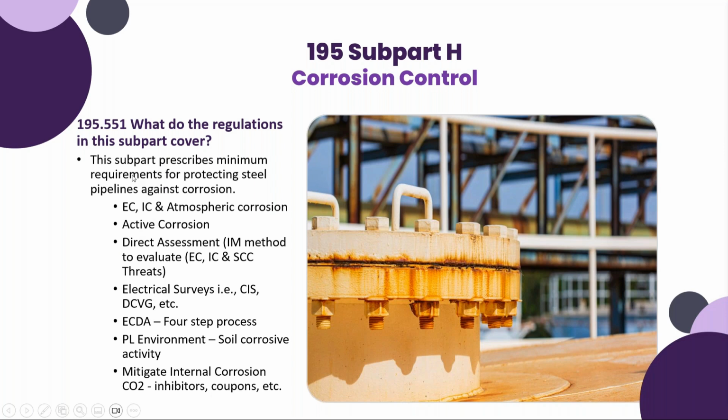I'm not going to repeat a lot of this stuff, but here we have a flange on top of a vessel here, and as obviously we could see, we got some corrosion on the flange faces inside here, and you can see the gasket. We have corrosion coming out between the flange faces.